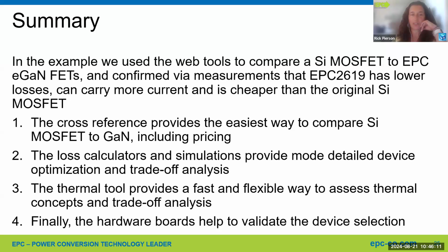Our first question is, would you recommend using EPC GaN FETs in series in the case of a 400-volt bus? No. Just like silicon MOSFETs, you cannot use these devices in series. The balancing of the voltages is entirely dependent on parasitics, and you cannot control those. So you need to have an active way to control the balancing of the FETs.